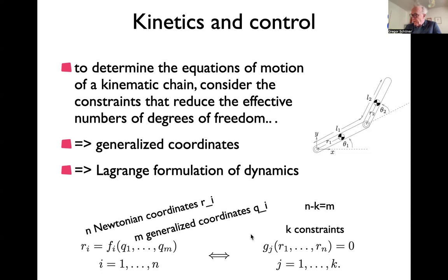So we have constraint equations that would eliminate almost all degrees of freedom. From 6 for every joint, you can eliminate all but 1. And it's a question, how do you do that in the equations? The Newtonian equations of motion become very complex. It's been done in some very older work, but it's not actually the current state of the art. State of the art is to go to the Lagrange formulation of dynamics.